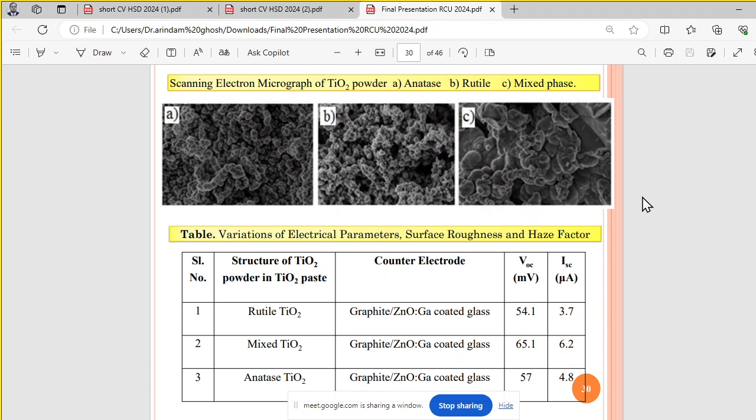Another example, in the next slide, I have shown a perovskite based cell, where a perovskite layer is formed on ZnO:Al and ZnO:Ga doped thin films. On a glass substrate, first of all, we deposited the ZnO:Al and another one ZnO:Ga film, and then we deposited the perovskite material on it and studied its performance, such as electrical, optical, etc.